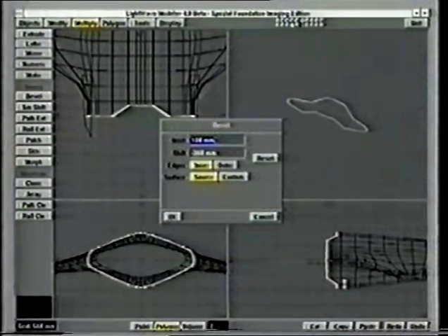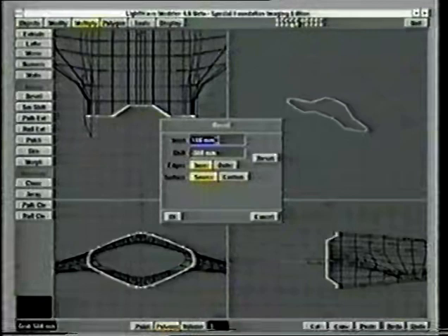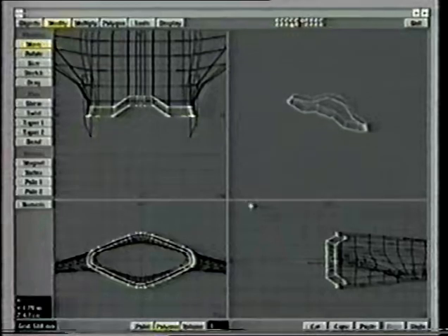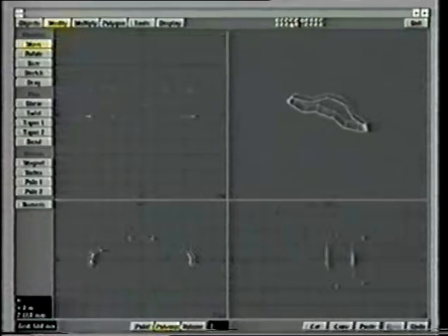But as it's getting narrower towards the back, obviously it's got to taper a little bit more on the inside, otherwise the inside surfaces will go through the outside surfaces, which you don't want. So I've got an inset of 100 millimeters, shift to -300, let's try that. That looks pretty good. You can see that the inner surface is moving in there. What I'm going to do is just manually move it back a little bit more, using the control key to constrain everything.